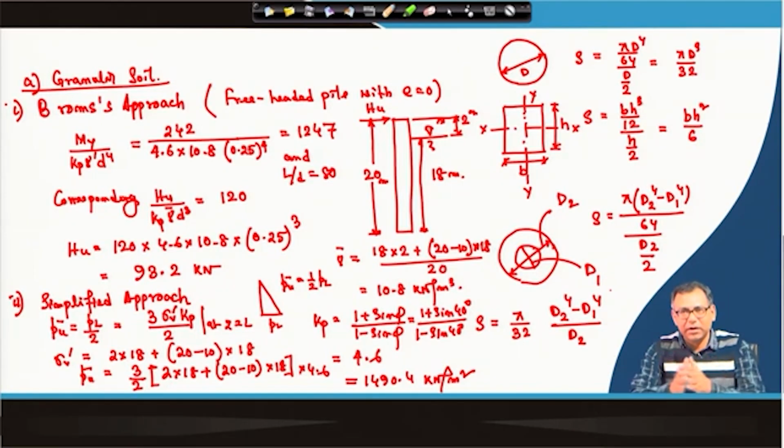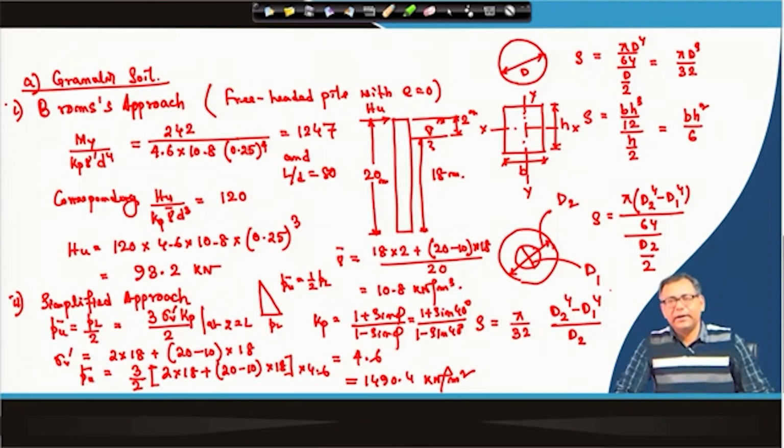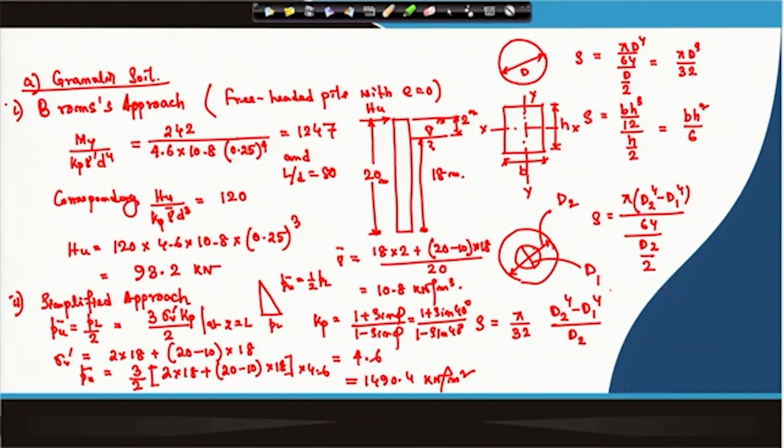But I would recommend that you use Brom's approach to determine the ultimate lateral load carrying capacity of the pile. In this section I have discussed the ultimate load carrying capacity of the laterally loaded pile. Next class I will start the settlement response of the laterally loaded pile, for both the single pile and the group pile.